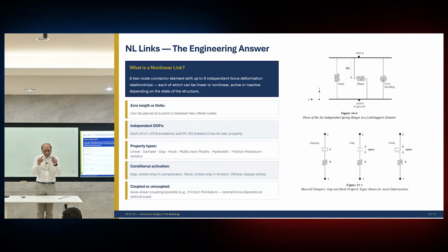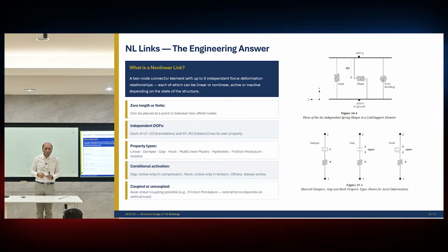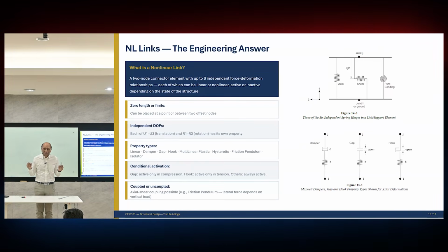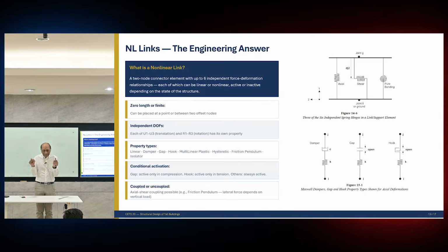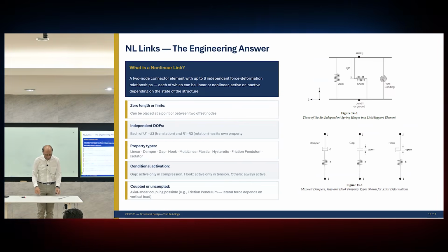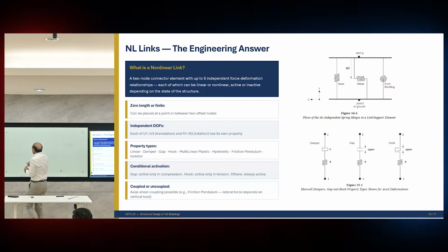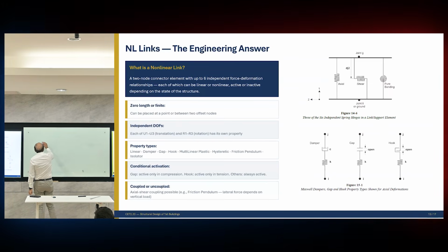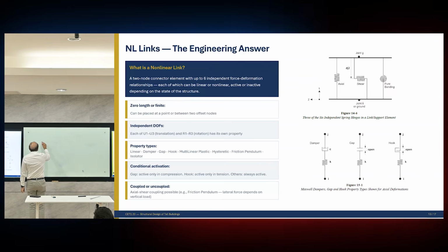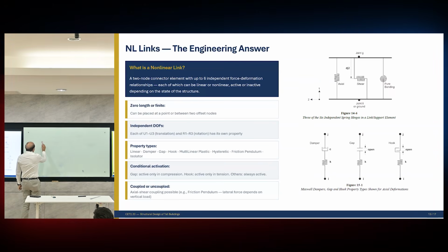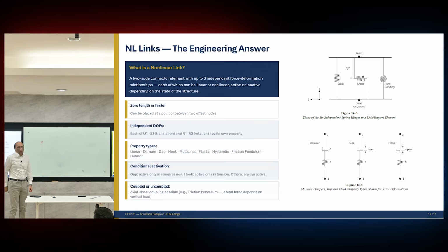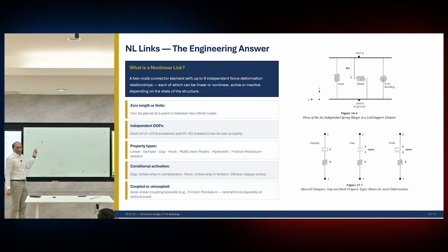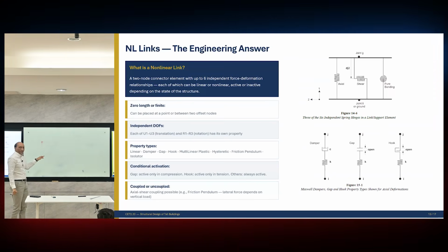Normally, when you make a frame, it automatically connects all the 6 degrees of freedom together rigidly. Here, we separate that node into 2 parts. This is very important for you to understand. Normally, when you draw something like this, the node, which I presented to you last time, is a single node connecting these elements. And this is rigidly connected. All degrees of freedom are continuously going through this one.